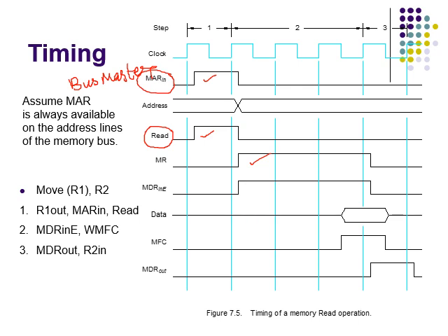That is, action 1 is to load MAR with the content of register R1, which holds the memory address. This is step 1, and action 2 was to start a read operation on the memory bus. So these two actions are being combined into a single control step.